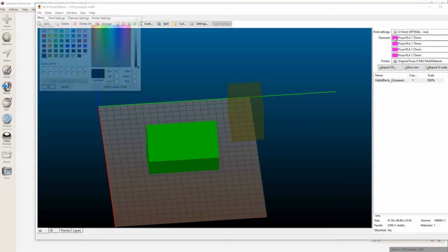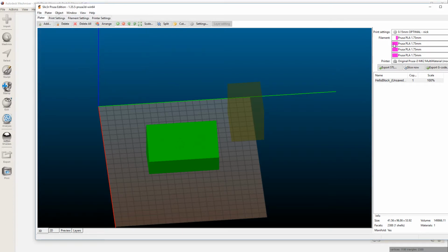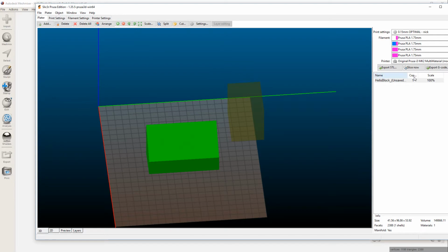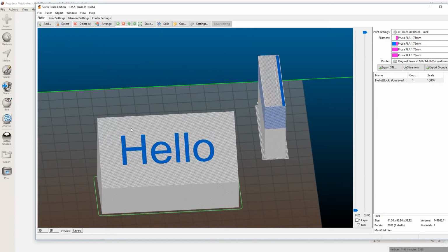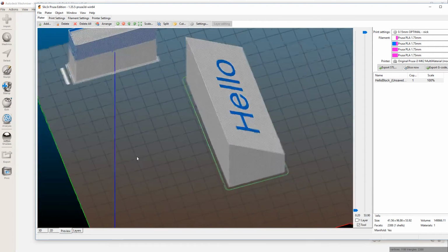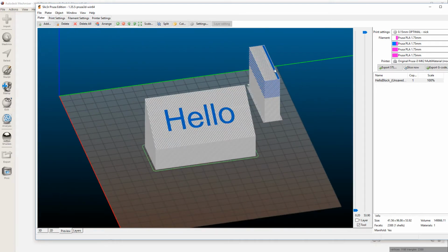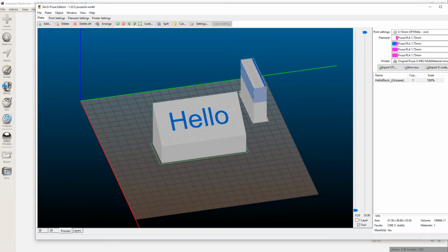And we can click on these filaments and say I want the base in extruder 1 to be white, and extruder 2 to be a baby blue. Let's try that. And we say slice, and we say preview. And we see what this looks like. The multi-material creates what's called a wipe block, and this is how it changes colors. It wipes and purges one color to the other during this.